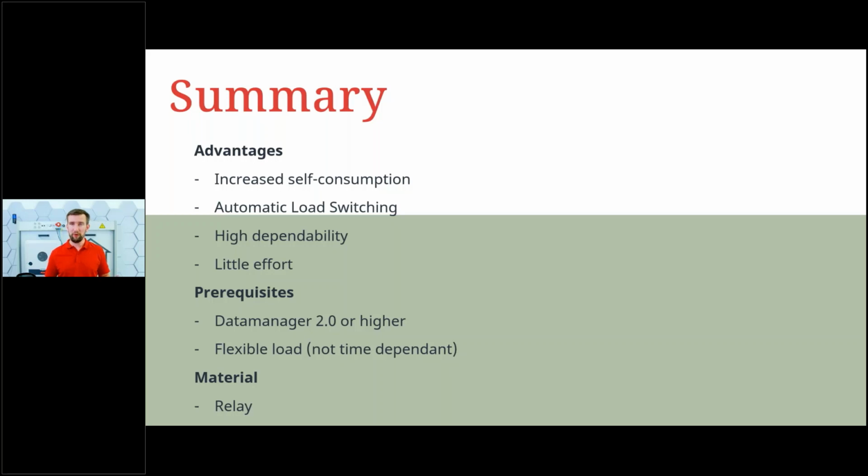What prerequisites do we have? Well, we need an inverter with a data manager 2.0 or higher, and we need a flexible load. Time flexible, can run anytime during the day and create that buffer effectively. Additional material, well, yes, we need some cables and we need the relays.